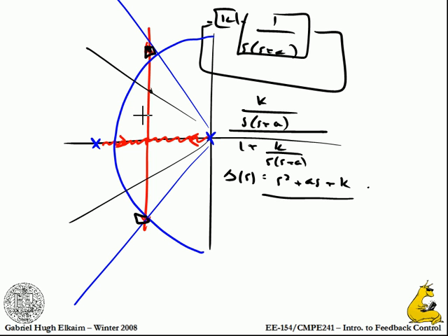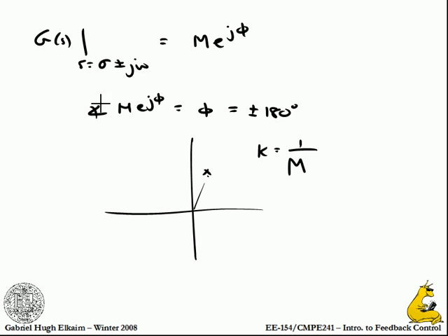So anyway, the whole point of what we're doing is we're trying to look for all of the places where the poles and zeros come from, and we're going to factor out one constant gain, one parameter that we're going to vary. We want to see where they move as a function of that parameter.